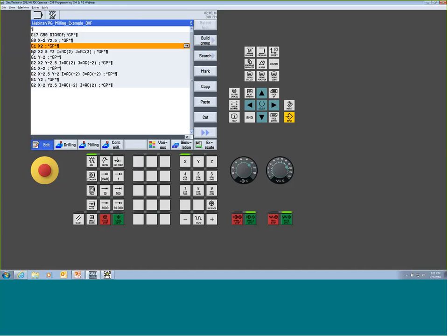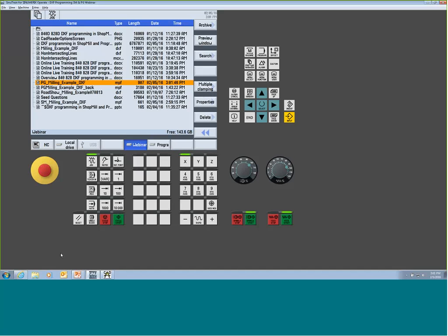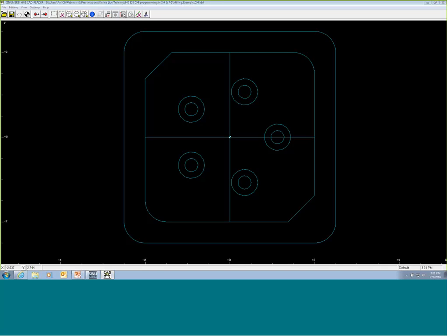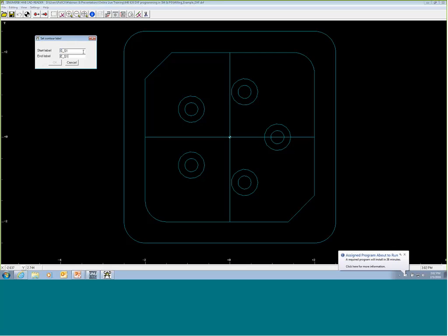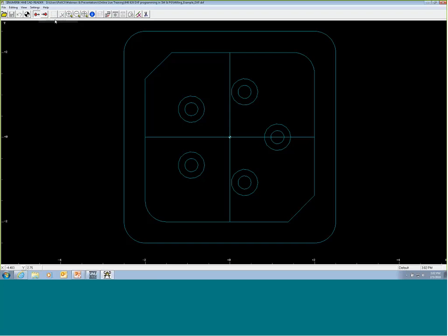So the labeling is going to come on either side of this specific geometry. So for us, if I had created the labels, the unique labels, I'm going to call this shape 1 or S1. I'm going to call it end S1. Say OK. So once the label's triggered, now I'm going to pick things the exact same way I did before. And we'll go grab the endpoint of it.